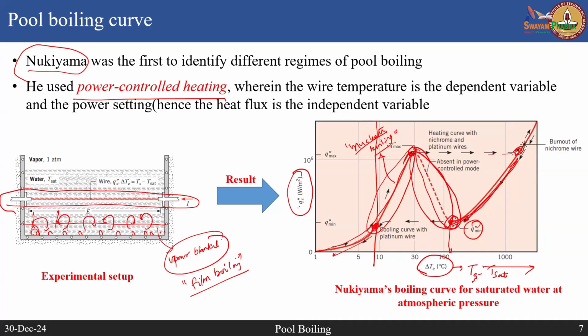So radiation becomes the most important mechanism for heat transfer, and not phase change. If you go almost to the melting point of the nichrome, the values of the heat flux almost match the values that you obtain with phase change in the nucleate boiling regime. To that extent, radiation becomes a very important contributor.